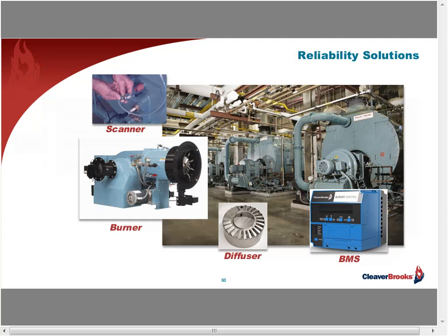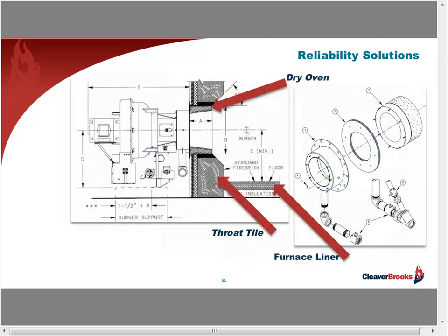So any issues should be documented in the inspection report so corrective action can be taken as quickly as possible, as should any issues with the diffuser that I mentioned previously. Then there's another area with the burner that needs to be regularly inspected, documented, and maintained, and that's the burner's sealing and insulating refractories I pointed out earlier. Now, failure to do so results in extended outages due to noxious gas formation and overheating of the burner housing or furnace, causing weld cracking and the need for immediate repair or replacement. So it's just more downtime.